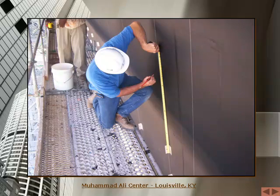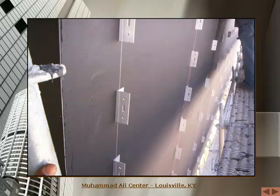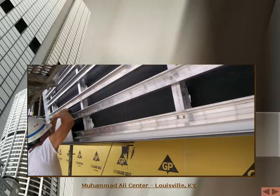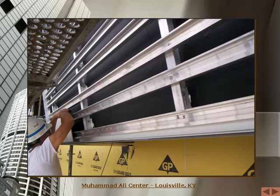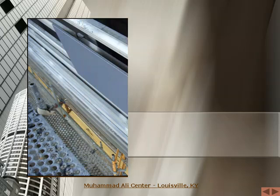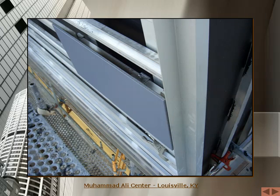Workers lay out the locations for the brackets along the structural building wall per specifications. Afterwards, vertical supporting rails are installed. These rails provide the means for connecting the horizontal rails in which the ceramic tiles will be attached. The horizontal rails connect easily to the air-sealed corners, which compartmentalizes the air barriers to allow for pressure equalization when wind loads are applied. The ceramic rain screen facade panel simply and easily snaps onto the horizontal railings.